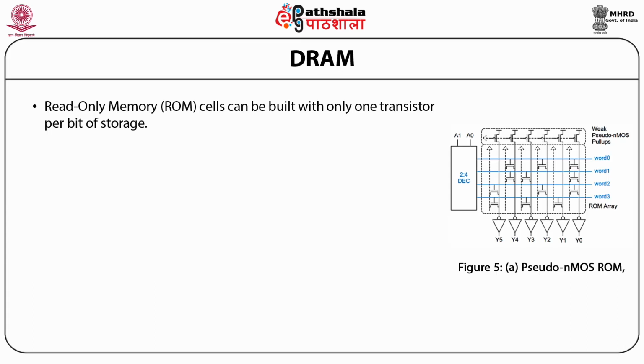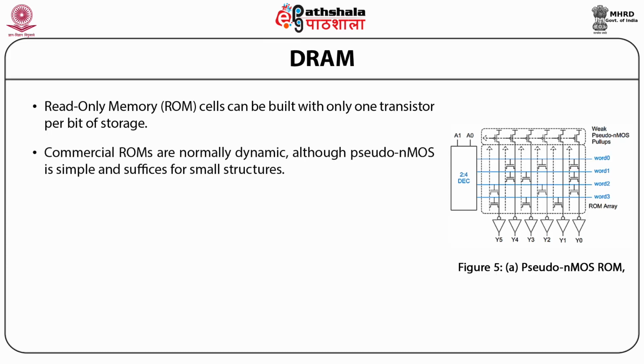A ROM array is commonly implemented as a single-ended NOR array. Commercial ROMs are normally dynamic, although pseudo NMOS is simple and suffices for small structures.